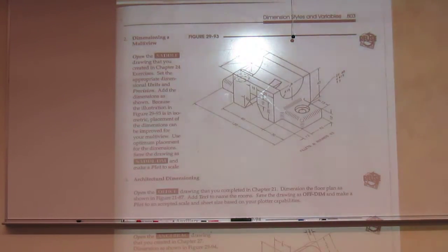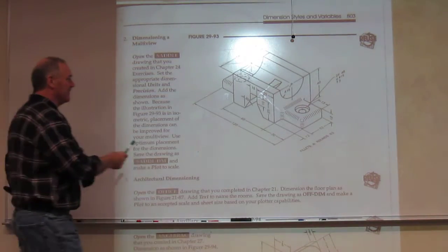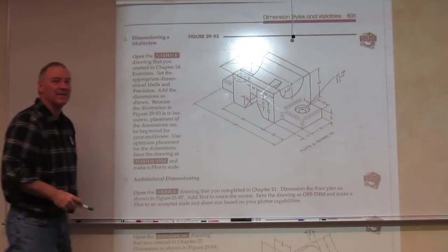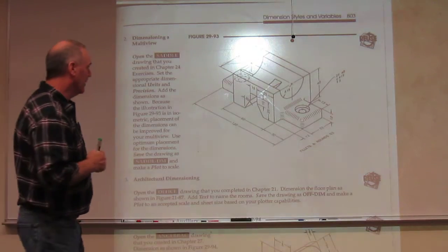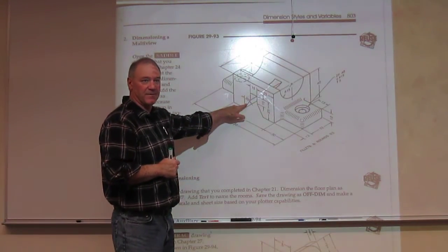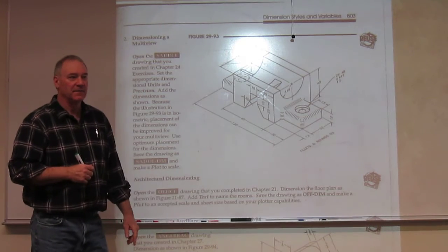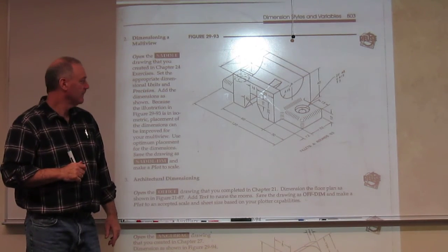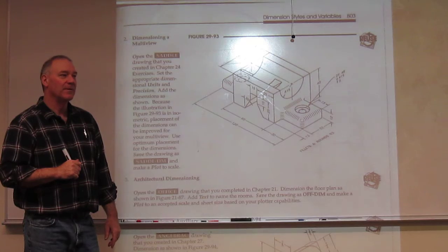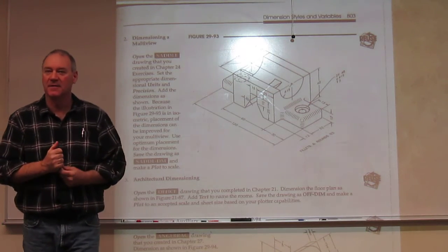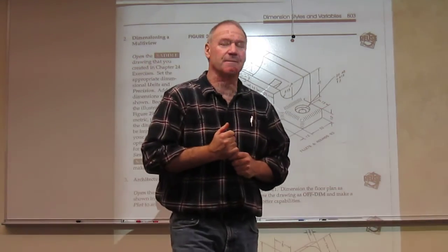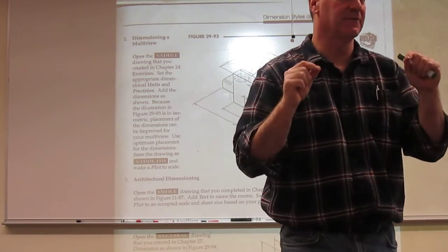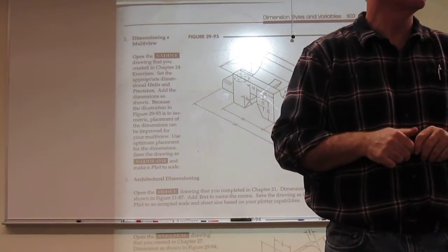This one also had a pretty tricky little surface. In essence, there's this little thing right here. I don't know that that one justifies an auxiliary view. It's not really a dihedral angle because it does occur on a normal plane, so you do see true size and shape of it from this view right here. So you don't need to pull an auxiliary. Whether you went to locate one side of the triangle on an angle or 2 points on the triangle is up to you. Remember, it is preferred to have the 2 points on the triangle, not 1 point and an angle.